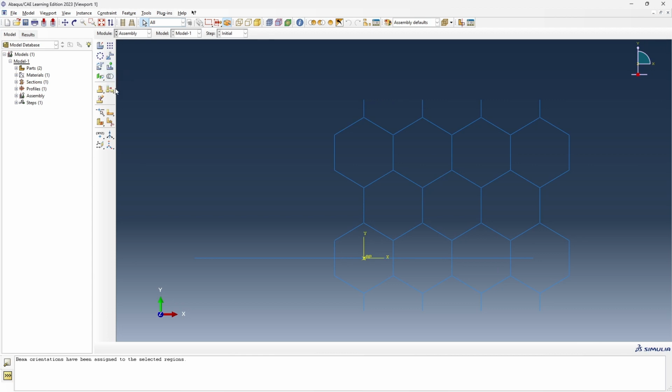So click on this point, click on this thing called translate instance, select this instance here, click done, select an access point, click on this reference point here, select an endpoint. If I made a 5 hexagon lattice, I would ideally have this single node here, but for now let's just click any of the points here because it doesn't really matter. I mean, it kind of does matter, but it's fine. So we have this, and we'll say okay.